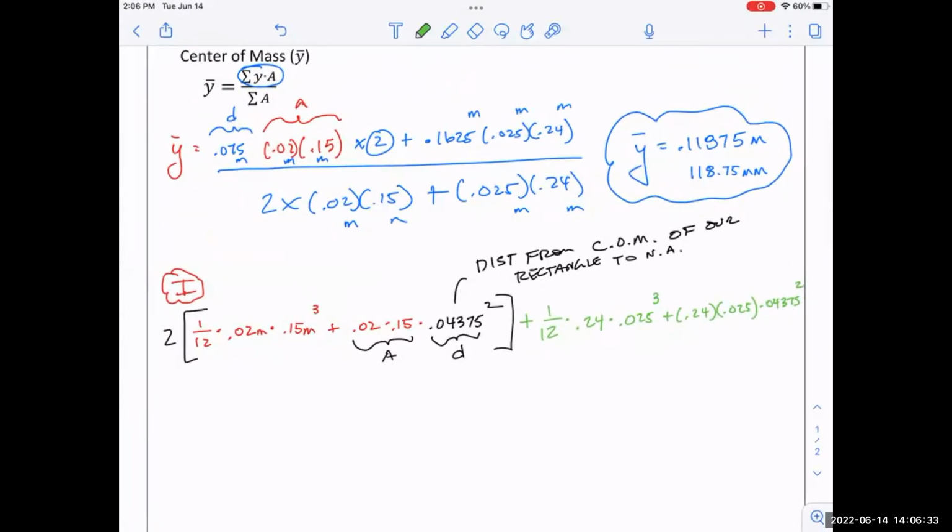Remember that, what does the I value tell you in simple language? I shouldn't say remember, because I don't think I've even taught you this yet, but in simple language, if I say, hey, this beam's got an I value of 97, what does that tell me about it? Its ability to resist shape changing. That's really what it's telling you. And it has to do with the shape of it, not the material. So this is just a rectangular beam, and so it'd have one I value.